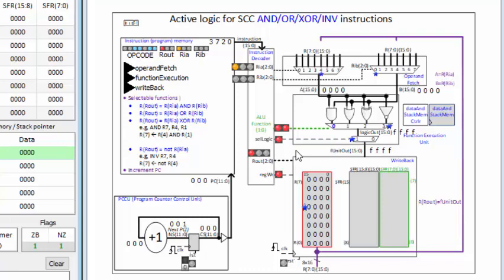The data and stack has not been used, and you can see that the 0 coming in from the register down here, register 4, is inverted through this to give FFFF and through it into the write back function. The red illustrates here that the register bank R has been written to index 4 given by the destination register, and reg write signal is inserted in the instruction decoder to make that write happen. And as is quite normal, the program counter is incrementing on the next clock edge.